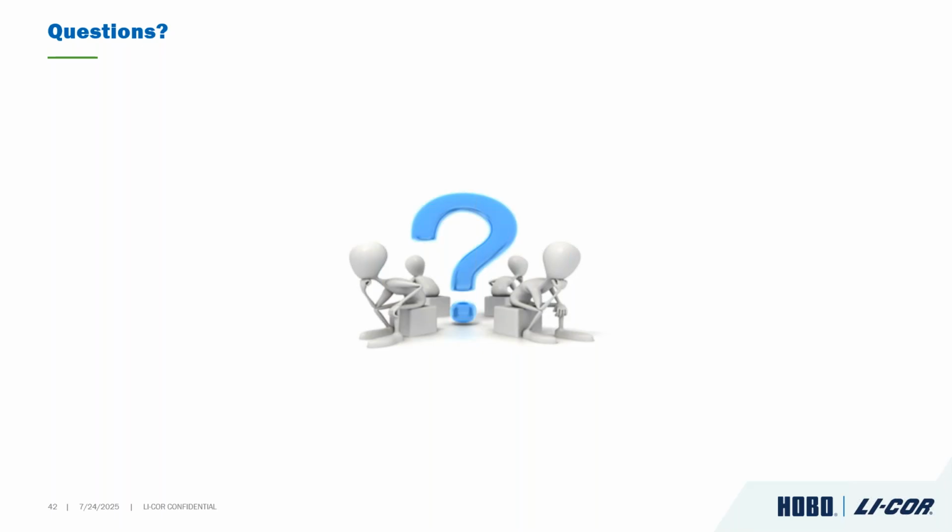Yeah, absolutely. So depending on the logger that you're using, it might be good to take a look at the device manual, as well as some of the resources that we have available on HoboWare, and even considering taking a look at Hobo Connect and using that software as well. Right, and with that too, you can configure your logger, and then when you download it, you can reconfigure. Once you reconfigure, that overwrites any data that was on the logger previously.